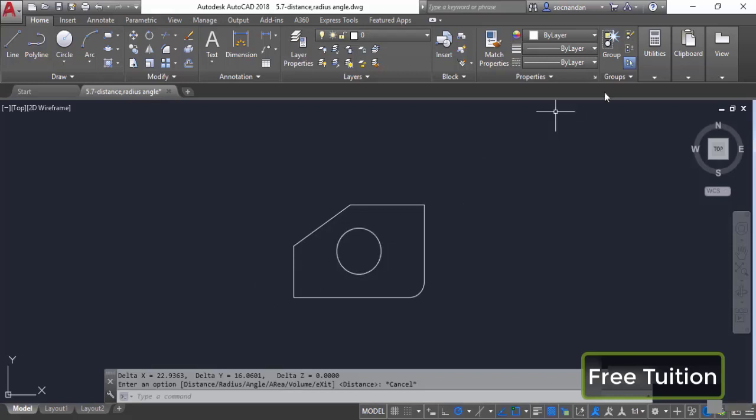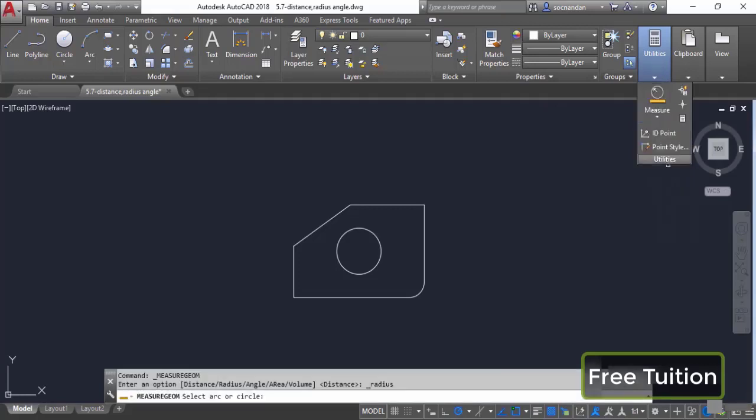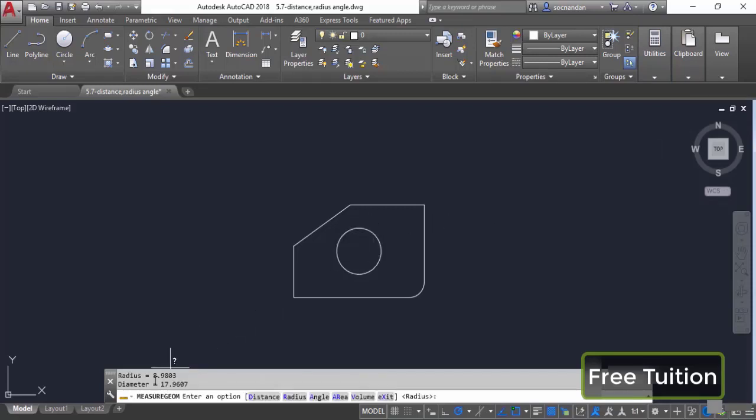In a similar way, you can use other options of this flyout to find other values. For example, here we have the radius. Select the radius and now select an arc or circle. So here we have the circle. Let's click on it and we have the radius, and not only the radius, we also have the diameter of this circle. Similarly, you can repeat the radius tool simply by selecting the radius option from the command line here also. And now click on this arc, and the radius is 6 unit, the diameter is 12 unit for this arc.